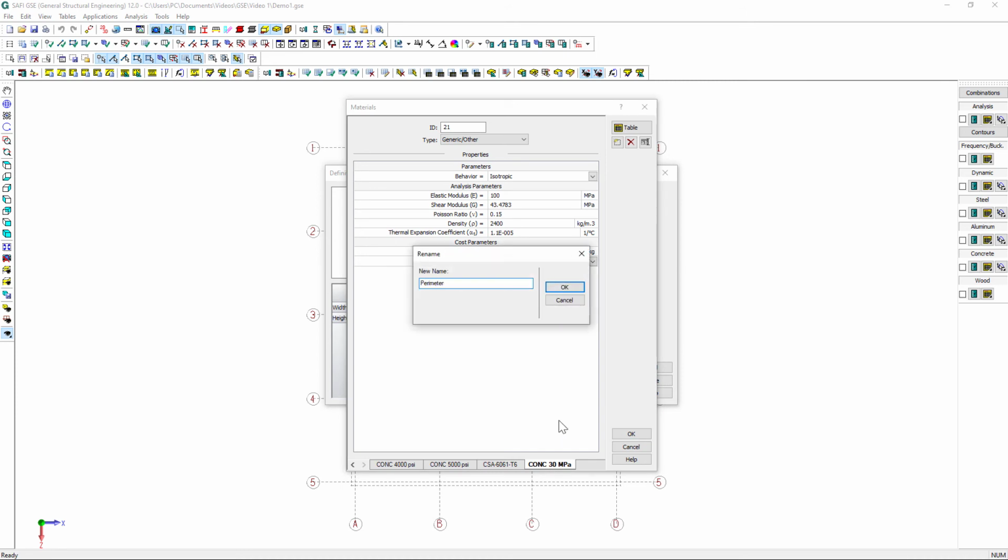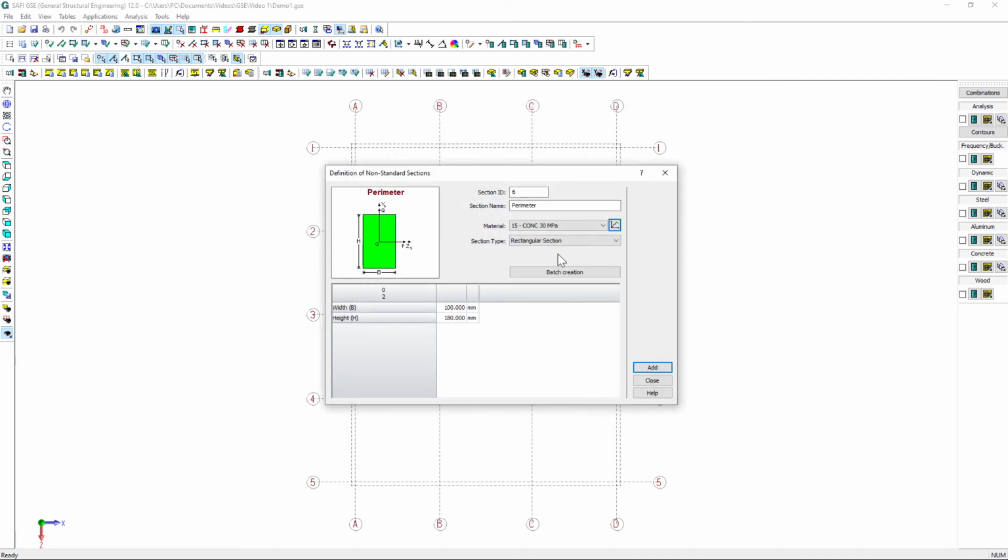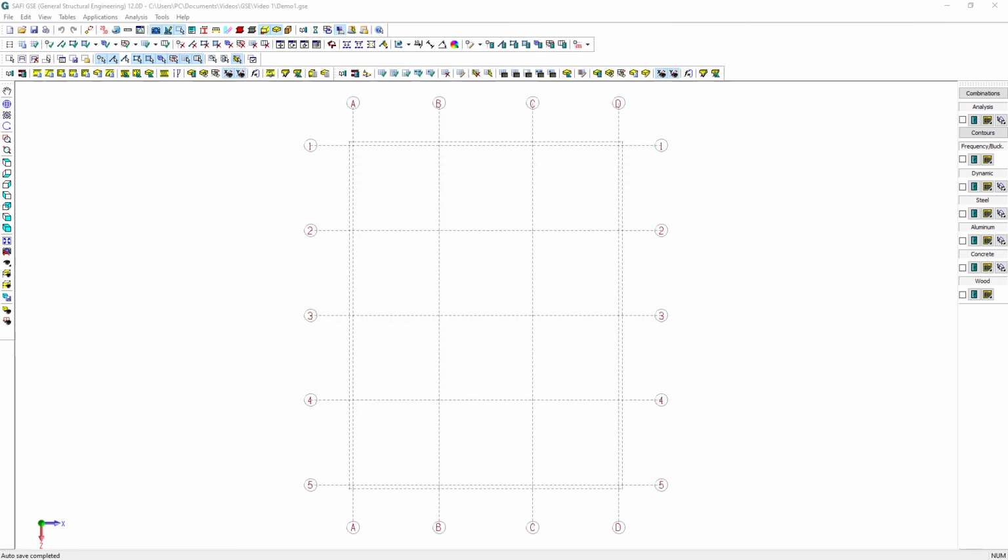When the grid is properly defined, the geometry may be quickly created. The model may be created in different ways depending on your preferences and work methods. We will simply show you one of the many ways that you can create a model. First, we will create the joints for the base of the model. We will simply select the Add a Joints command and click at every intersection of the labeled axes, from A to D and 1 to 5.